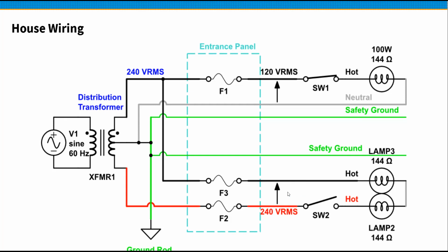My shop is wired that way with a neutral. So I have all the receptacles split. One side of the receptacle is the black phase, the other side is the red phase, and they share a common neutral. So that if you've got stuff plugged into both of them, it reduces the current flow through the neutral because they're in opposite directions. So if it was perfectly balanced, you'd have no current flowing in the neutral.